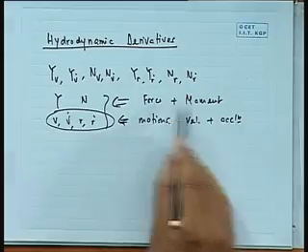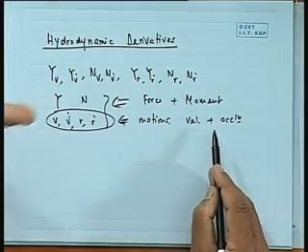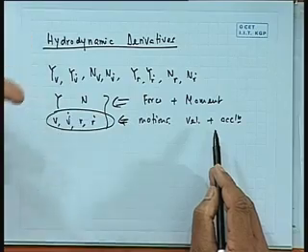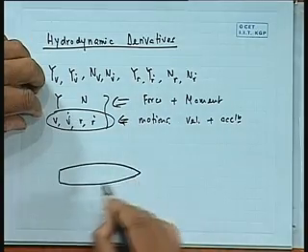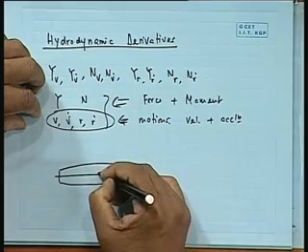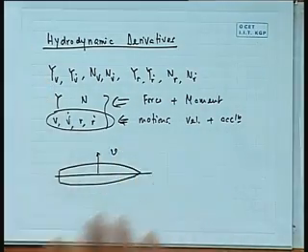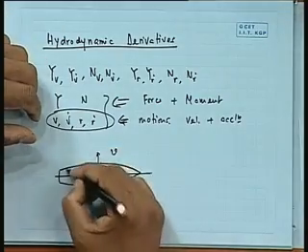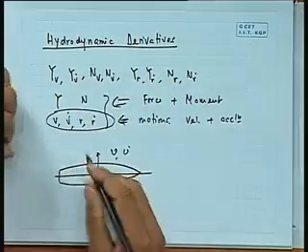So, the derivative of force and moment against any of the velocity and acceleration, of course yaw and sway, is what we call a hydrodynamic derivative. What is the meaning? Take a ship here. I try to give a push, I try to give a v here. The moment I try to give a v or v dot here, I am basically shifting it that side.